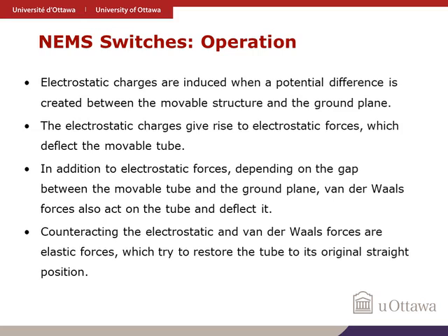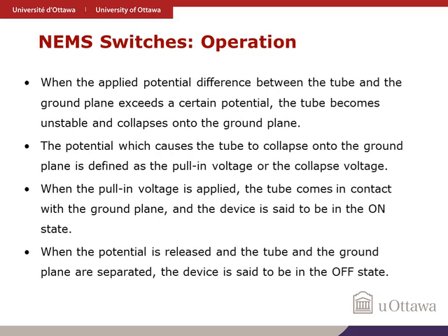Counteracting the electrostatic and van der Waals forces are elastic forces, which try to restore the tube to its original straight position. When the applied potential difference between the tube and the ground plane exceeds a certain potential, the tube becomes unstable and collapses onto the ground plane.